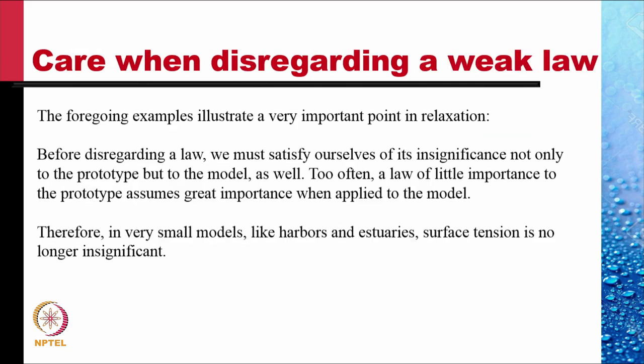This example illustrates a very important point in relaxation. Before disregarding a law, we must satisfy ourselves of its insignificance not only in the prototype but in the model as well. Too often, a law of little importance to the prototype assumes great importance when applied to the model. Therefore, in very small models like harbors and estuaries, surface tension is no longer insignificant unless we increase the depths.